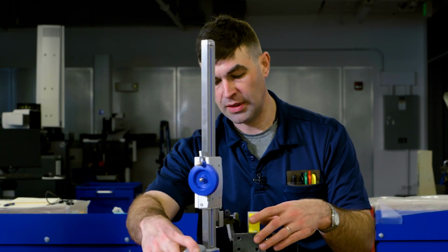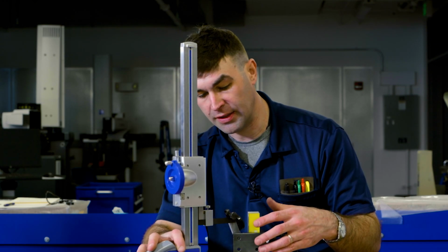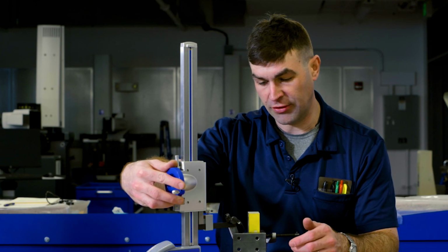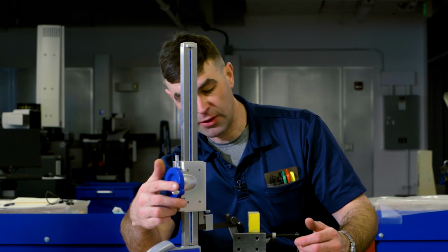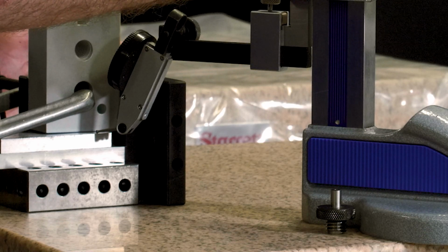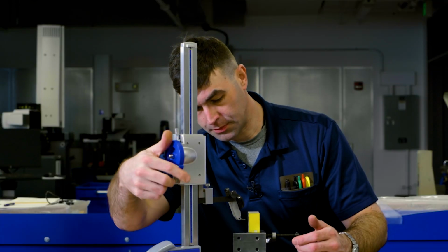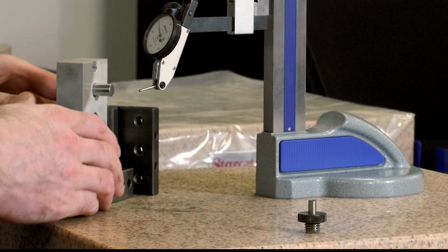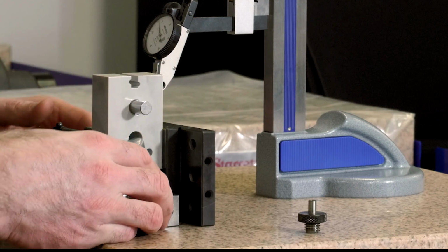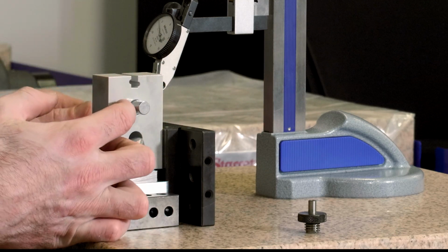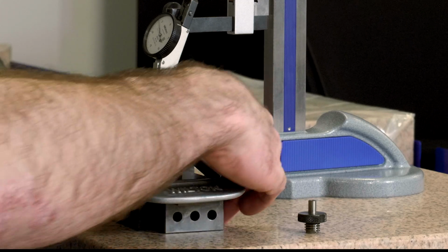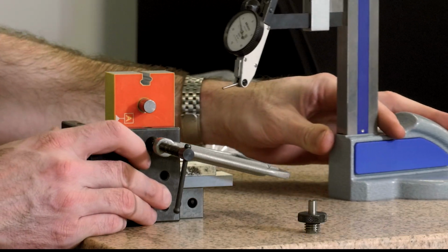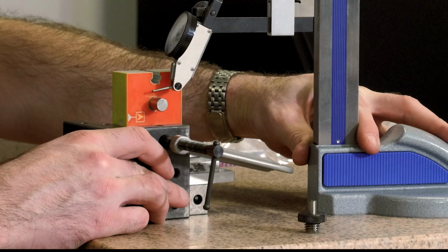Okay, now I needed those gauge blocks so I can get a 0 off of that. Right, the blocks are just kind of an extension of our datum simulator. Going back up. So we're all set up. We did this side already, which I've called the near side. I'm going to spin around and get what I call the far side. And I call it the far side because it's normally the one that's kind of out of our reach because it's contacting our simulator. Lower down on here.